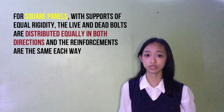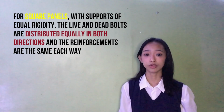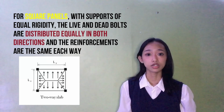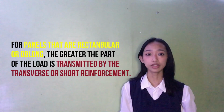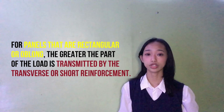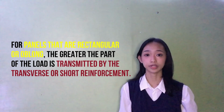For square panels with supports of equal rigidity, the live and dead loads are distributed equally in both directions. The reinforcements are semi-equal. For panels that are rectangular or oblong in shape, the greater part of the load is transmitted by the transverse or short reinforcement.